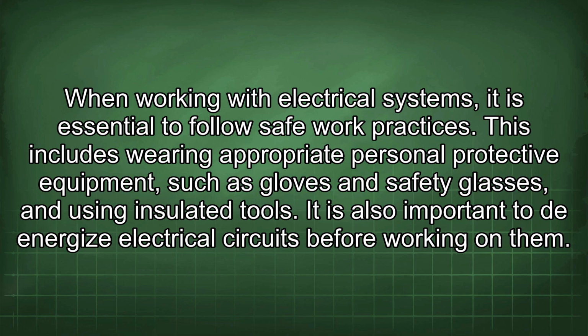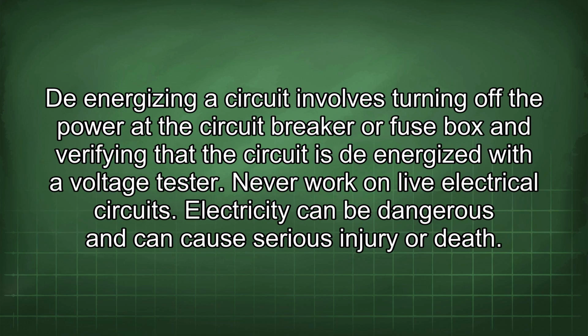This includes wearing appropriate personal protective equipment, such as gloves and safety glasses, and using insulated tools. It is also important to de-energize electrical circuits before working on them. De-energizing a circuit involves turning off the power at the circuit breaker or fuse box and verifying that the circuit is de-energized with a voltage tester.